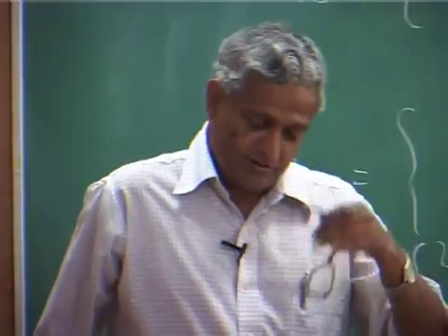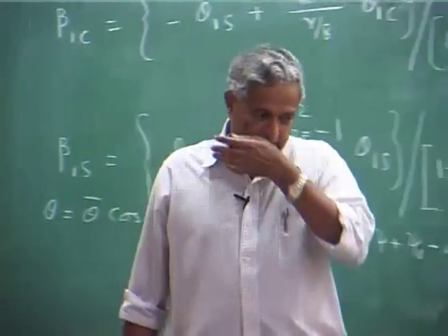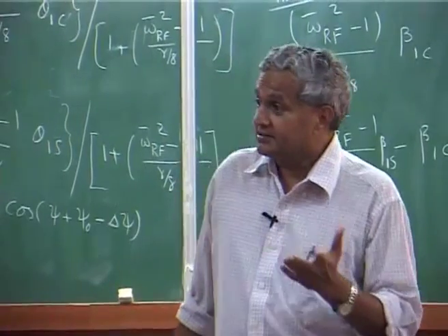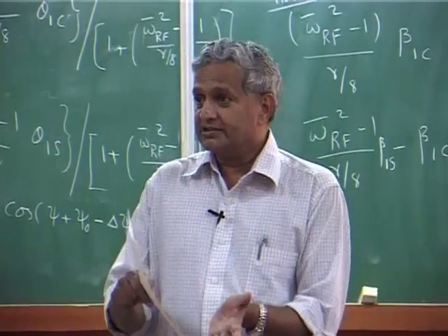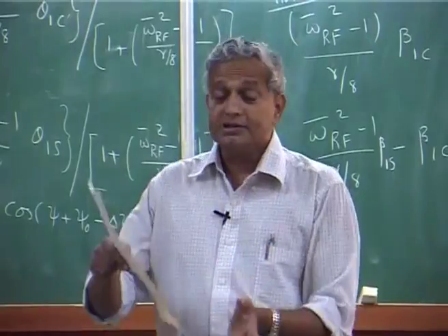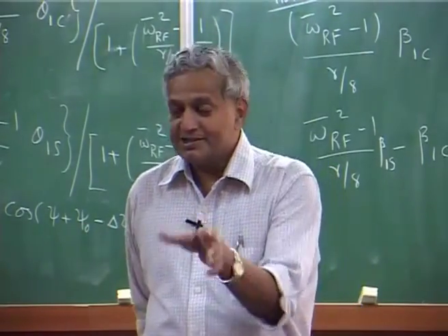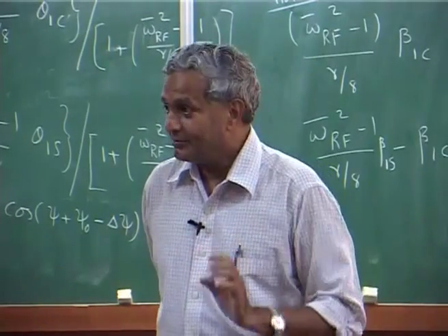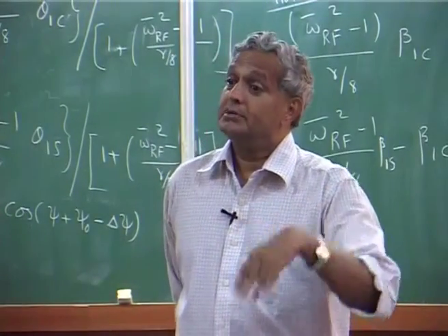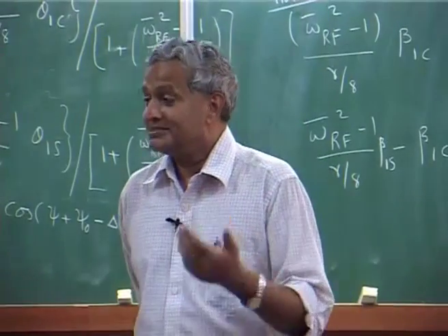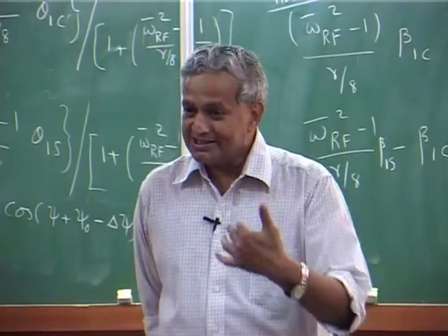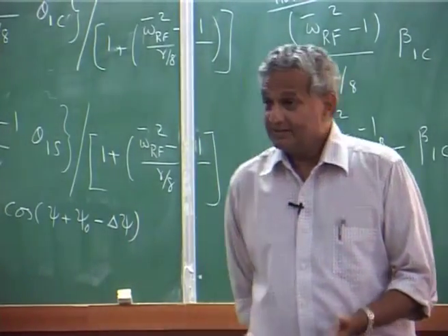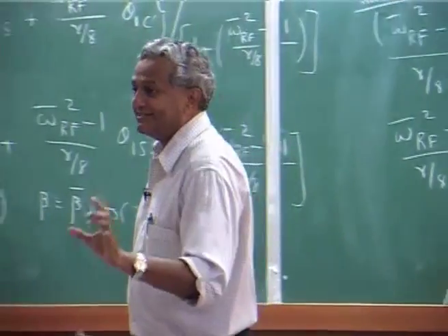It is not that you do not pitch, you will roll. And particularly when we, I hope there will be some time for analyzing the flight dynamics. The inertia of the vehicle is different in pitch direction and roll direction. Pitch it is larger, roll it is less. Now, if the inertia is less, what will happen is if the pilot gives an input for pitching down, actually he will roll much more than what he intends to do in pitch itself. That is because of the less inertia in the roll direction. Now, this coupling is very difficult for the pilot to fly.